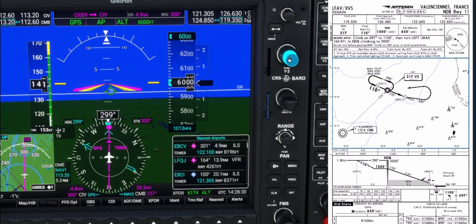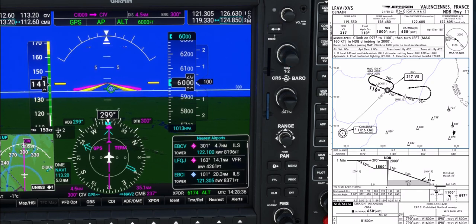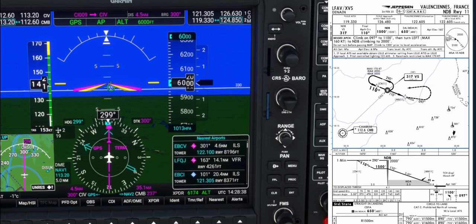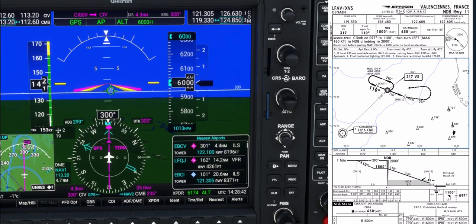Once the SID is finished, we are in the cruise mode where we have to take care of our cruise alternates. Once we are taking care of our last en route alternate, we also have to compute the top of descent as we are approaching destination. We add 30 miles to the top of descent computed distance, and that's the distance at which we have to prepare our approach, add some miles taking care of any tailwind.